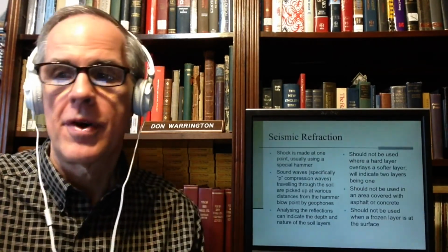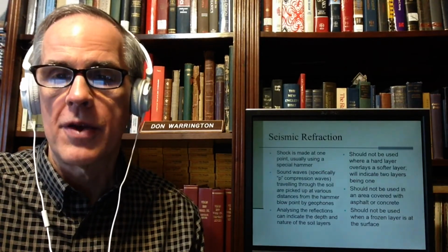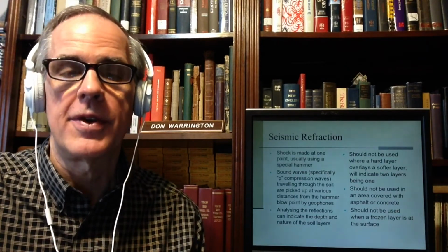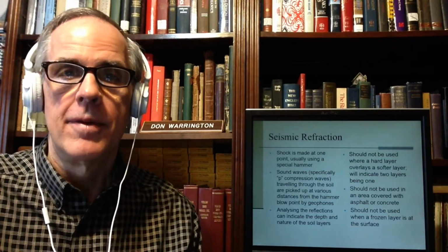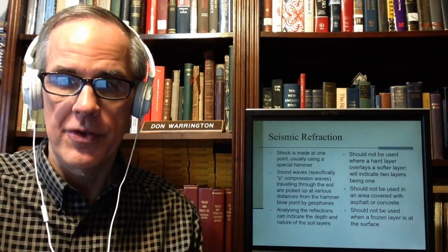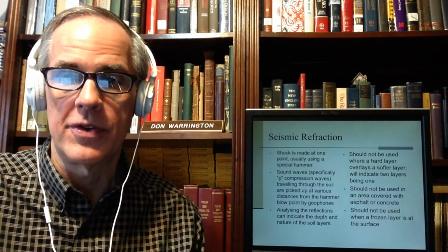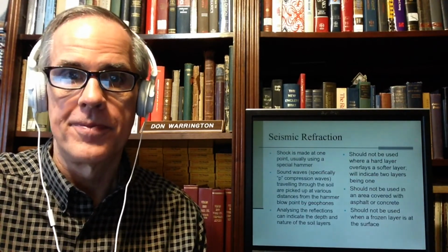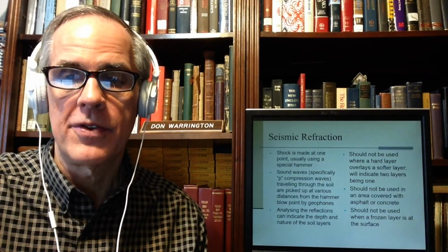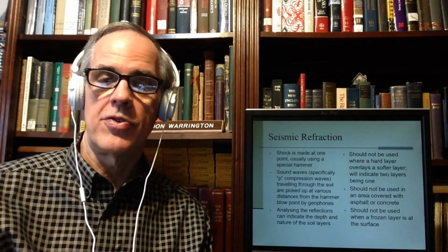Seismic refraction, we'll start with the first one. Basically, you use a special hammer to make a shock at one point. And then sound waves, P compression waves, you've got P waves and S waves, which are important for seismic purposes, travel through the soil. And sound travels through soil just like it does through air and water. And it's picked up at different points, and you can actually analyze these to find out the depth and nature of the soil layers.